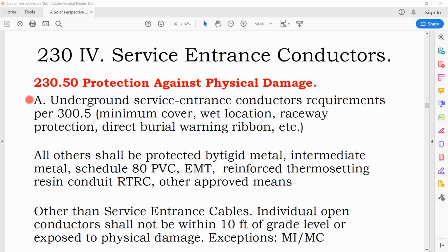I had a client who was insistent on putting conduit between his battery house and his house, but his battery house was uphill of his house. And basically all he was doing was installing a drainage system that drained from his battery house directly into the foundation of his cabin and increasing the labor cost to boot.